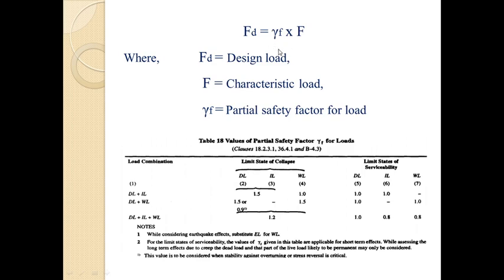The values of partial safety factor for loads as per IS 456 2000 are given in this table. You can see clause number 18.2.3.1 or 36.4.1.